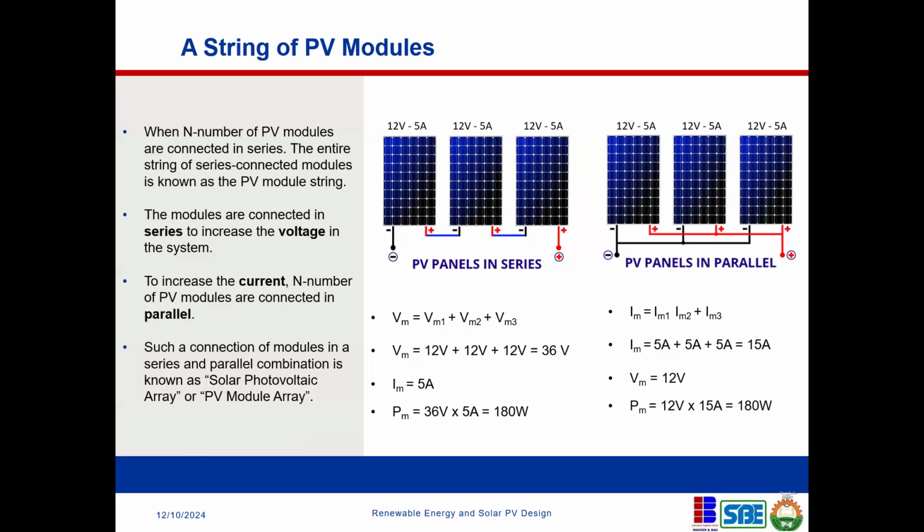Okay, good. Now this kind of configuration is also applicable to your battery system. You know, when I was talking about battery, we talked about parallel and series configuration. The same thing is applicable. If you want to increase the voltage of a battery to meet certain requirements, you have to add them in series, okay, to get a certain voltage for your input design system.